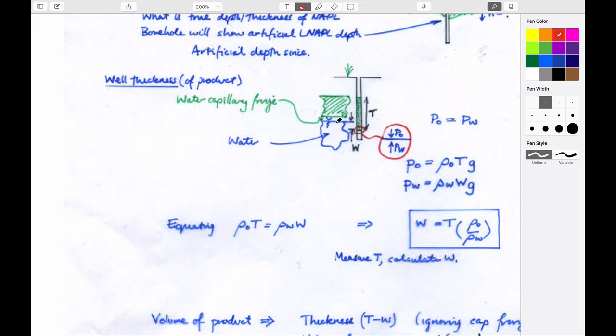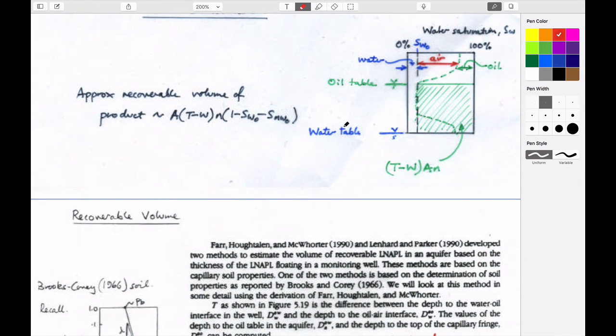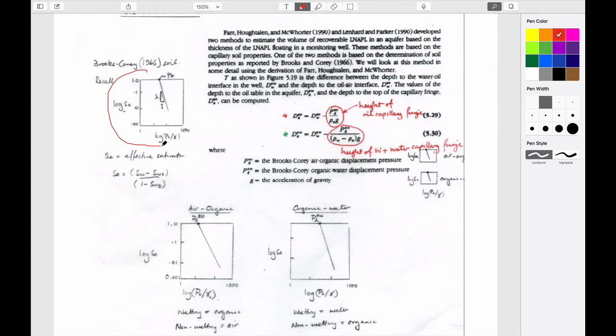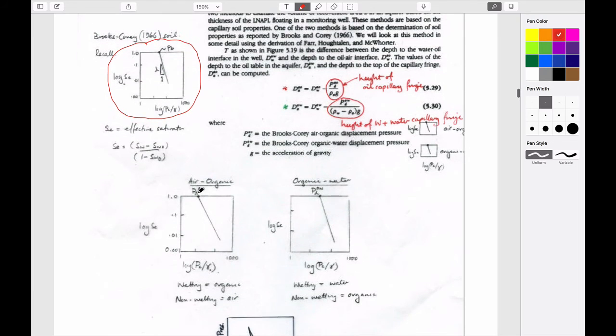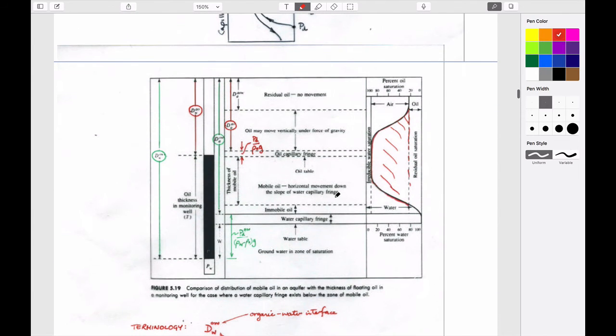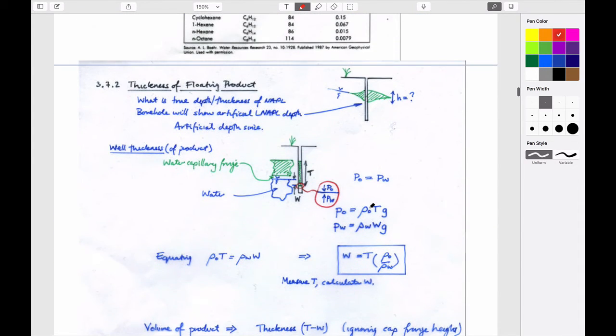One way to do this is to look at the capillary pressure curves, which define the saturation. One convenient way is to take these capillary pressure versus saturation curves for gasoline and air mixed together, two-phase fluids that have some capillary pressure curve, and gasoline plus water mixed together that have a capillary pressure curve, and combine them in some complicated way to figure out a more sophisticated way of defining this behavior that represents the true response that we have here.